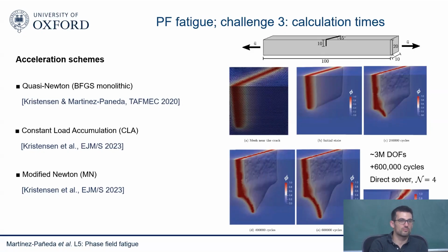So I guess you could either incorporate it that way. The reason why we decided to incorporate this nonlinear kinematic hardening, so enrich the constitutive model as opposed to the phase field degradation function, was that we felt that this way we would be more linked to the existing knowledge. So we know what the back stress is, what the strain hardening exponent is. We could go to a table and pick parameters as opposed to enriching a function. But I guess you could do it.